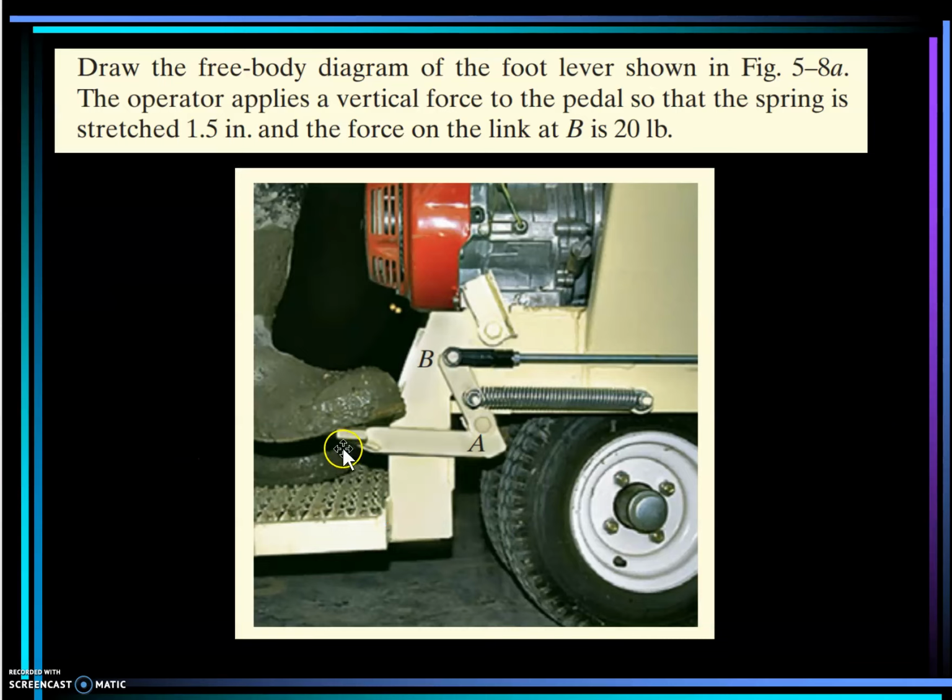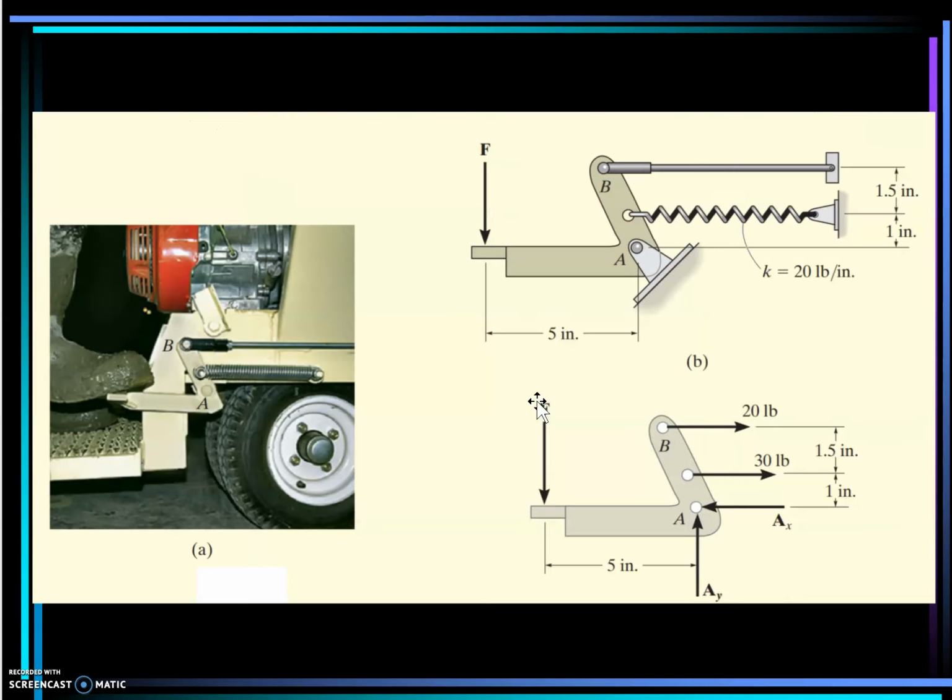Move on to another example that we talked about. If I press here with a certain force that I don't know, I'd like to quantify it. I developed a force in this link right here of 20 pounds, and I developed some sort of force in the spring, knowing the K of the spring and the stretch of 1.5 inches. I can identify the force in the spring. Here is the free body diagram. You find the force in the spring, or given the force, in the bar. Then I would like to get the force F.